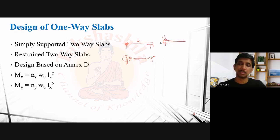That means this end is fixed now. It cannot freely rotate. There is a compressive action which will restrain this end. So this end in this case is considered to be restrained from rotating. So that is another case, case B, and this is our first case, the case of a simply supported slab.